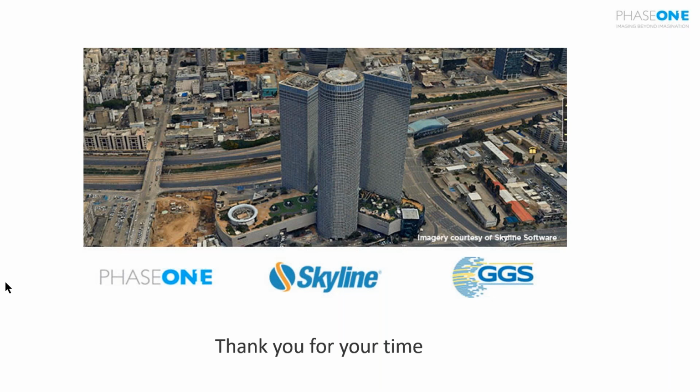There is a question, do you offer a way to post-process the 3D mesh to improve edge sharpening and area flattening? Yes, we have built-in editing tools, and we also allow to export the individual tiles as OBJs and edit them, and then bring them back to the software to produce the pyramided full output. So the editing can be done on a specific area for improvements, as well as we have built-in editing tools for removing cars from the road or cleaning out building facades, extruding them or smoothing them out.